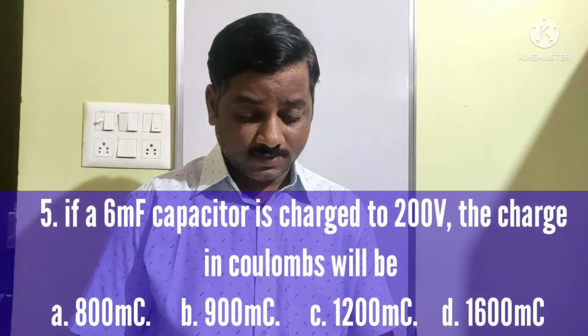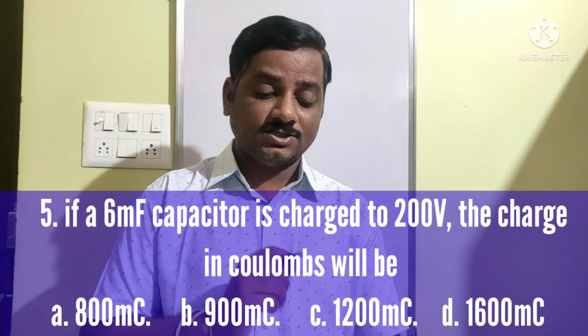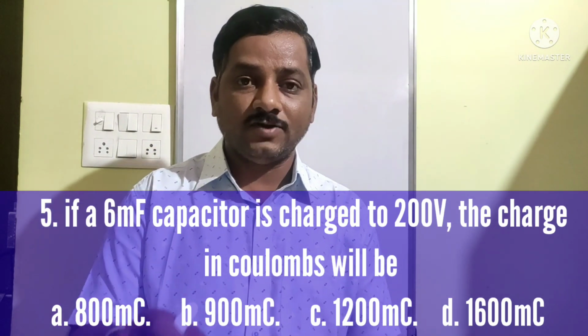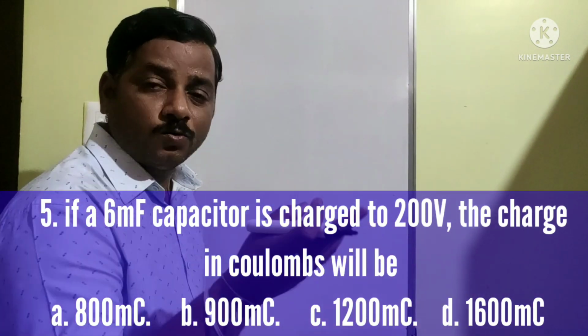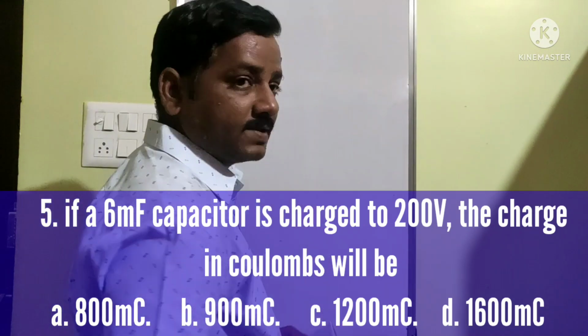Next, let me take the last question for today's session. If a 6 millifarad capacitor is charged to 200 volt, the charge in coulombs will be dash. So how much charge in coulombs do we have if the capacitor is 6 millifarads and voltage is 200? Again related to capacitor, voltage and charge. So we have Q is equal to CV.